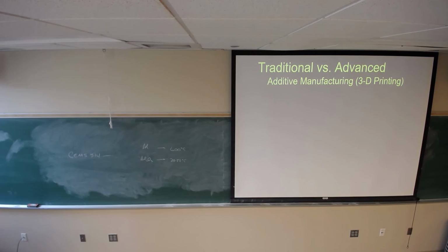All of the problems that we face in traditional ceramic processing, and I'm not saying traditional as in clay-based systems, everything that we face in our conventional ceramic processing is present in 3D printing. We just choose to ignore it. And so we have a 3D printing lab. We have two binder jetting systems, where you put down a layer of powder, and then you print the binder where you want the material to remain. We have two of those. They're interesting. And then we have one which is photolithography.